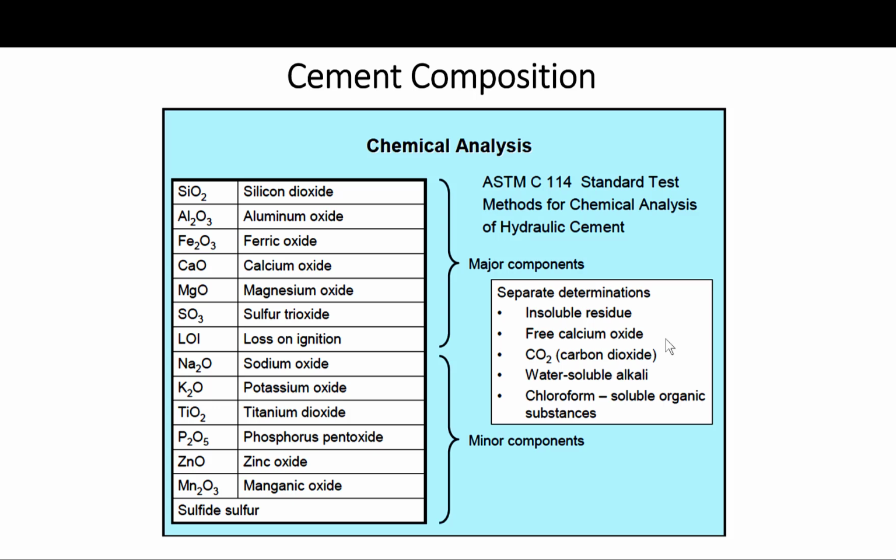As the determination of the particle size distribution is either cumbersome or requires extensive or expensive equipment, it is a common practice in the industry to obtain a relative measure of the particle size distribution from surface area analysis of the cement using the Blaine air permeability method, ASTM C204. We will go over it. These few points I just wanted to mention here. Of course, everything I mentioned here we will go over one way or another in the coming lectures.